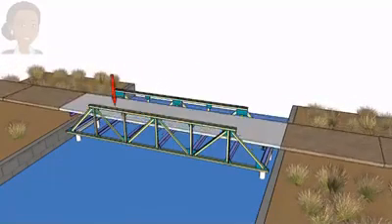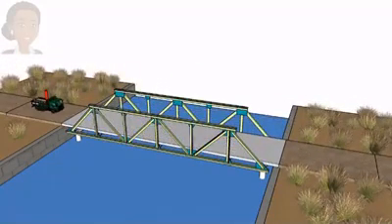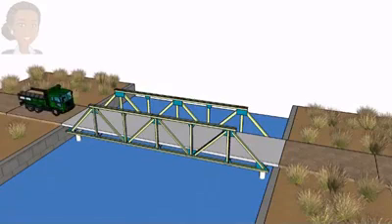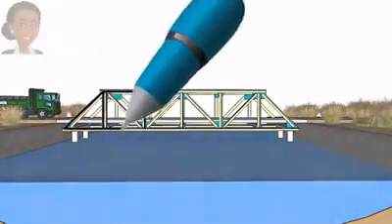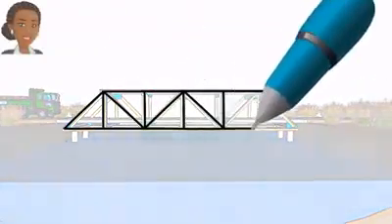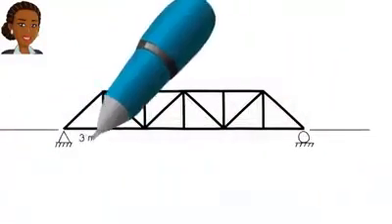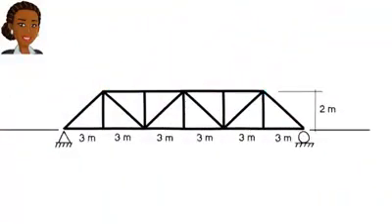We use this moving load pattern to construct the influence line for a truss member. However, in drawing the influence line, we only need to consider the loading cases in which the load is directly on top of a beam. All the in-between cases would be automatically captured by the straight lines that we draw when constructing the influence line. Let's draw the influence line for one of the truss members. Say for member AB.